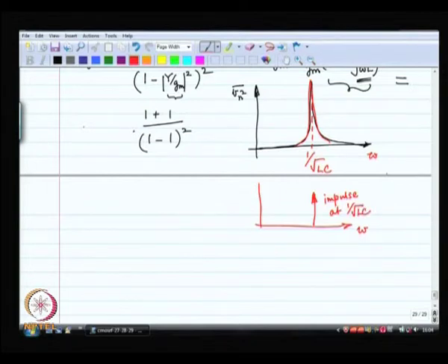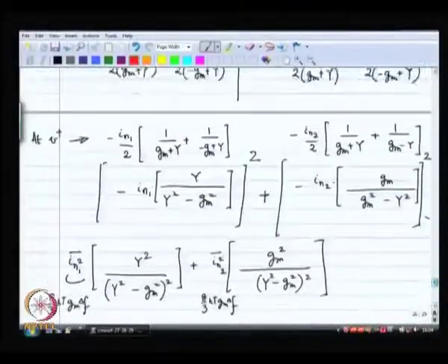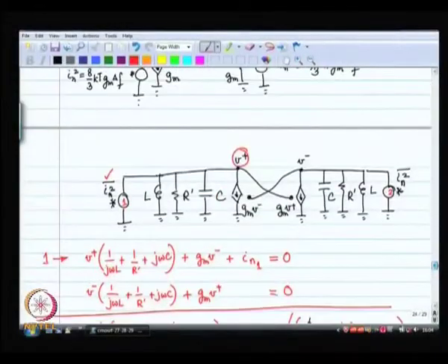Instead, because of noise, channel noise in the MOSFETs, I did not even talk about noise in the resistors, but there is going to be noise in the resistor. There is no real resistor over there, it is a resistor because of the losses in the inductor, but that will create noise.